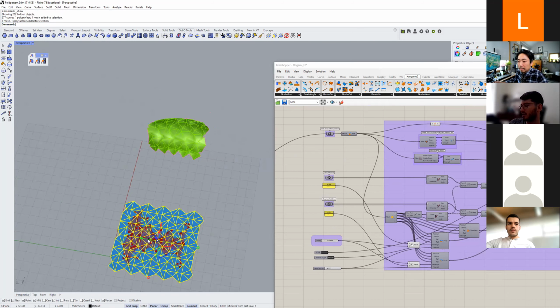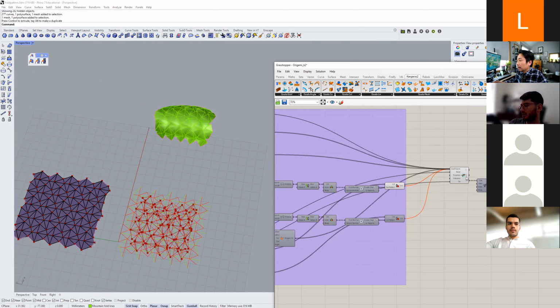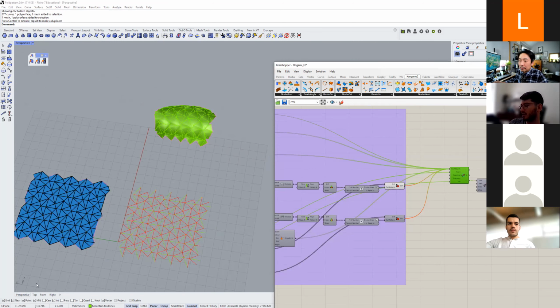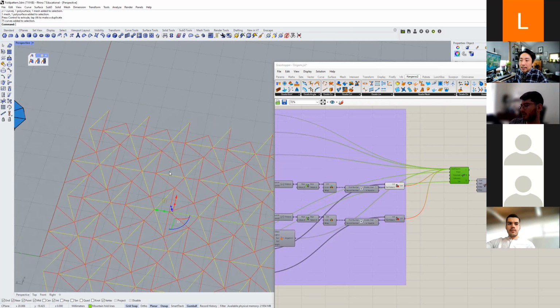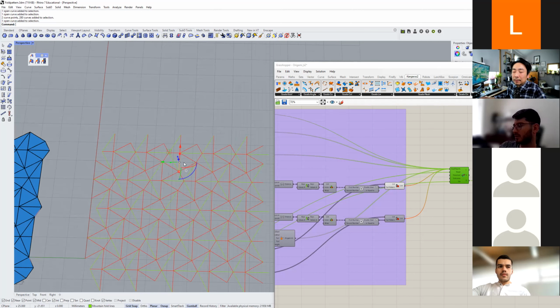For the Zund machine, what you will bring is the original file where you have these lines, the valley fold lines and the mountain fold lines. And then you want to extract the outline of this shape. That's the cut line. So this file will do a double-sided score, not cut, right?